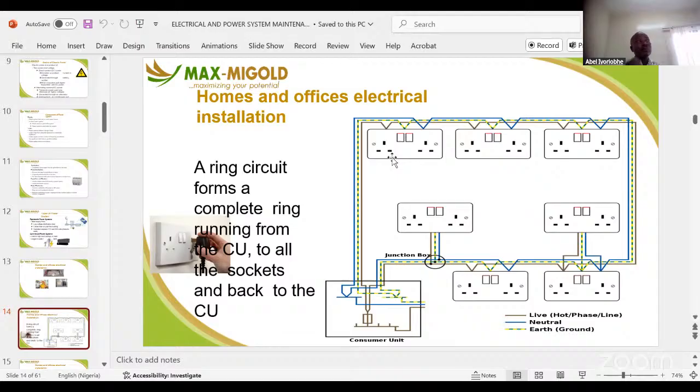The ring is where people loop cables from one point to another, undermining the source of that power. Maybe a 1.5 mm or 2.5 mm cable is the source bringing the supply. You are looping there: you put your oven, your washing machine, everything.